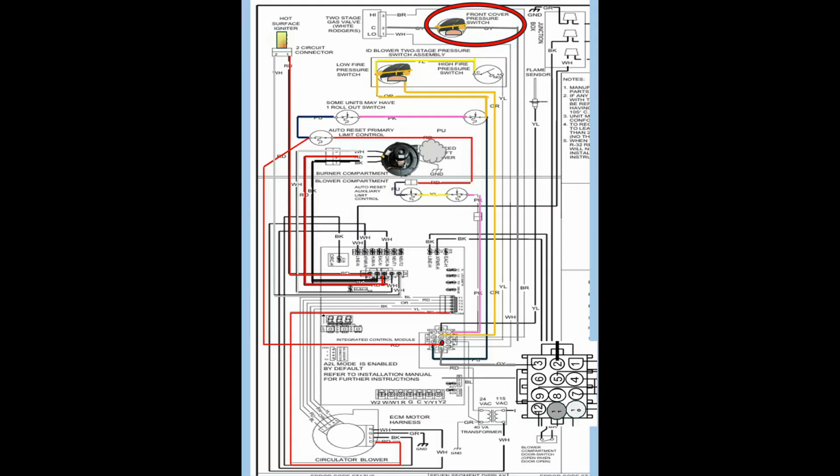After completion of the igniter warm-up period, the first stage of the gas valve is energized by pin 10 of the 12-pin connector plug and goes to the gas valve low side on a white wire. And yes, that is a grayish wire, but obviously I can't use white on white. It doesn't show up very well.